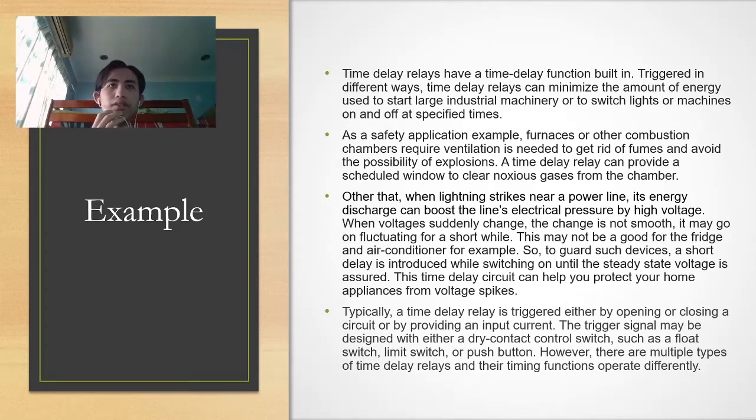As a safety application example, furnaces or other combustion chambers require ventilation to get rid of fumes and avoid the possibility of explosions. A time delay relay can provide a scheduled window to clear noxious gases from the chamber.